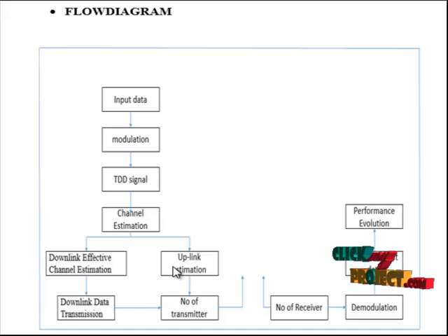We further analyze the structure of the channel matrix in the frequency domain. Next, in the downlink, effective channel estimation has been proposed. The downlink estimation is based on known data from either the transmitter or the receiver, placed over all the subcarriers or just over some of them, which is the case used in practice to reduce the overhead, pilot symbol assisted modulation. The case of all pilots is often used to simplify the treatment.